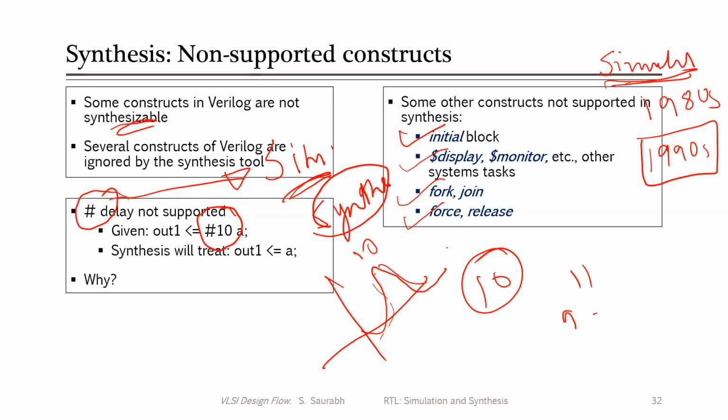Okay, so see, in all the design process, what we design is not for a particular value. We don't design a circuit element to produce an exact delay of 10. We always design within a range. Okay, we say that the delay of this circuit element should be within, say, 8 to 12 nanoseconds or time units, right?